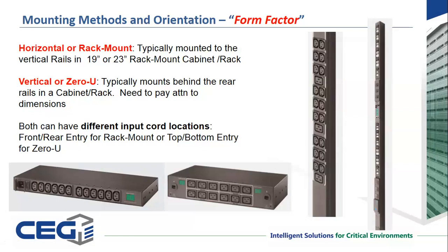So an example of that would be if there's a slab floor data center and the power is being routed to the cabinets overhead through a busway or some other means, you don't want to have the input cord of the PDU coming out the bottom of the PDU, and then it's going to have to get routed up another 7 feet just before it leaves the cabinet. You'd want the PDU coming out the top, or I've seen people actually install these things upside down.